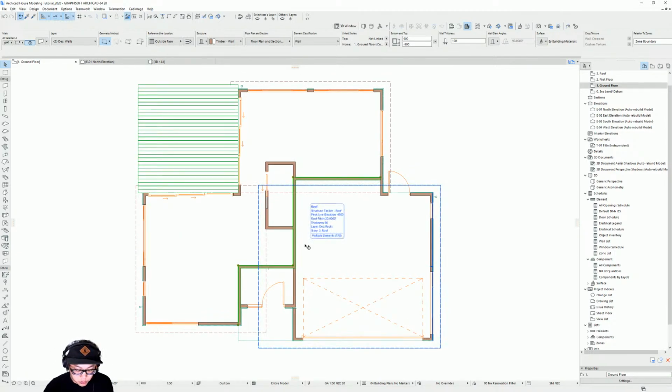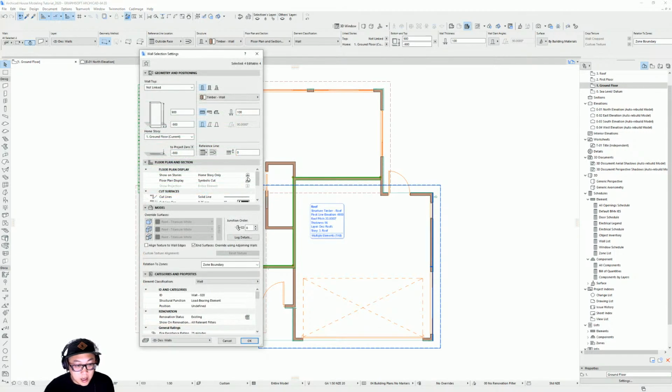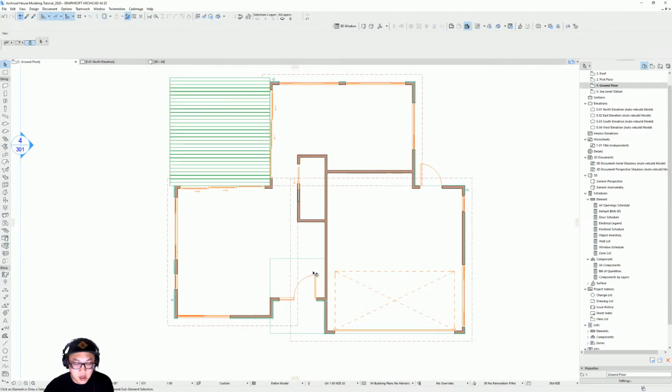So what you can do is you press Control, and I want to show them that only. Now they disappear. Because I think when you have the floor plans, it's actually the software cutting the house at a certain level. Right now, I think it's set up to maybe 1.5 meters off the ground floor, and because our walls are just 900, that's why they're not showing in here.